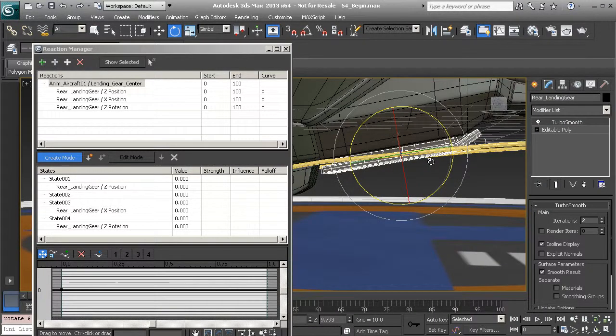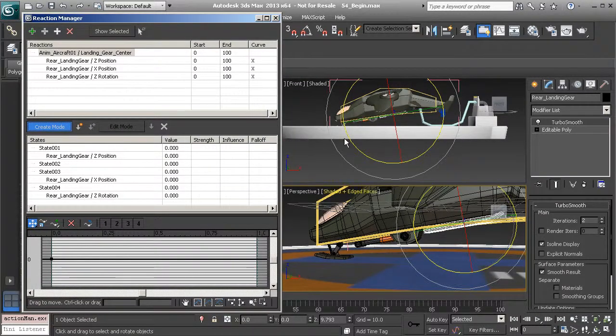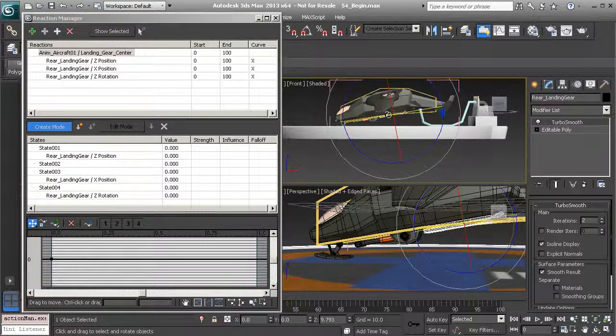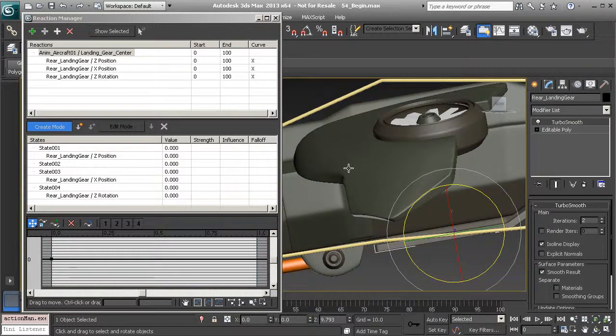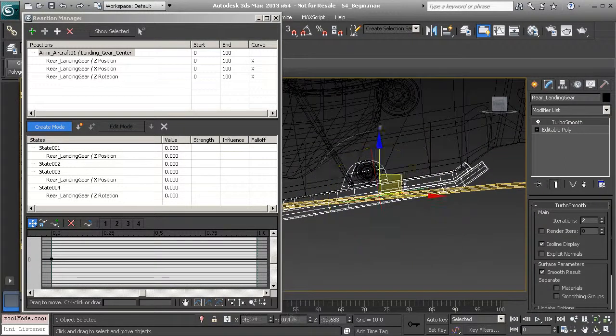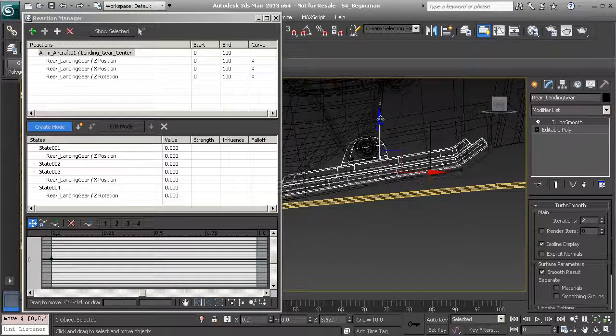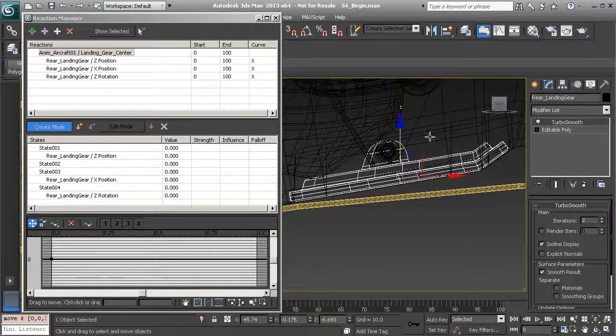From there, what I'd like to do is press Alt W to switch over to our 4-panel view, just to find a nice side view for our airship, which right now is our front view. So I'll right click in the front view panel, press Alt W so we can zoom in and just focus in on it. And now we can press F3 to go to wireframe mode so we can make sure that this fits properly within its socket. So let's start to adjust this a little bit more. I'll just translate it up in the z-axis, and I think we are good to go.